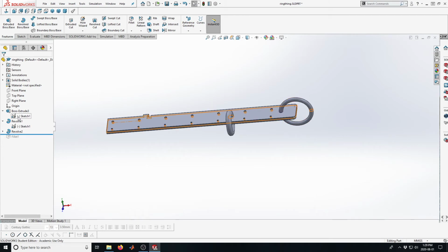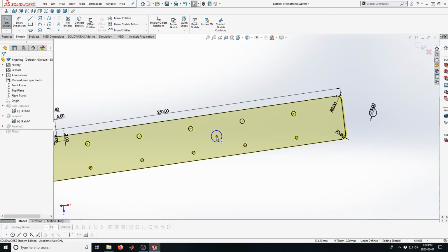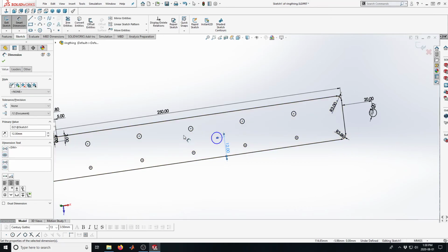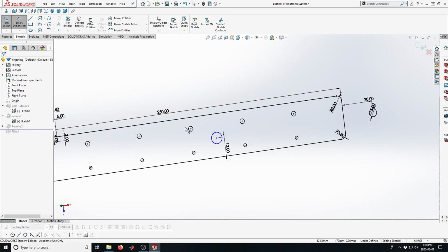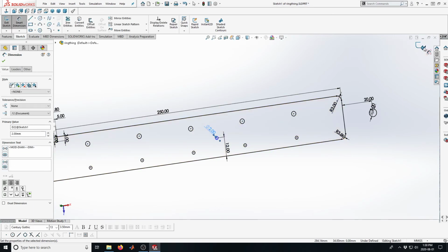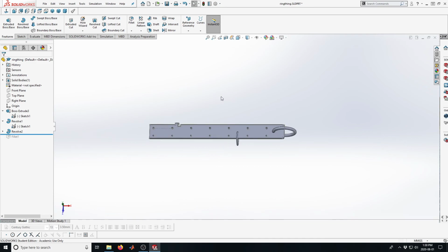Don't shy away from adding all the detail you can eventually. Don't need to do it at the start. You can start to build things up with just rectangles and whatnot, and then you can get more fancy. But keep in mind that everything is editable and everything will eventually break. And then if you can practice some of these good interrelationship rules, then that will help you in making sure that things are as robust as you can make them. Dimensions are a good thing. And you want to put those dimensions in sketches if at all possible. And those things will be reflected in the finished product.